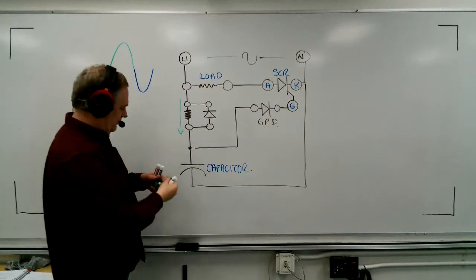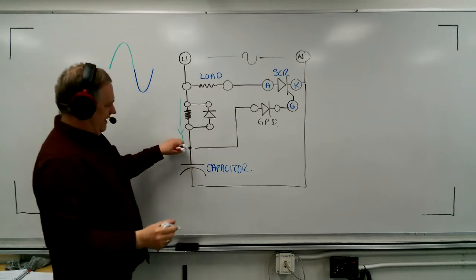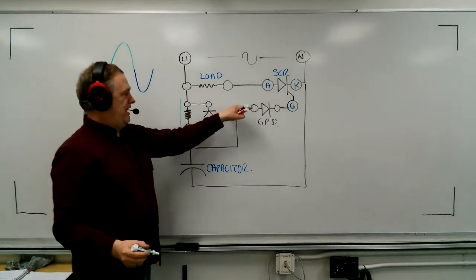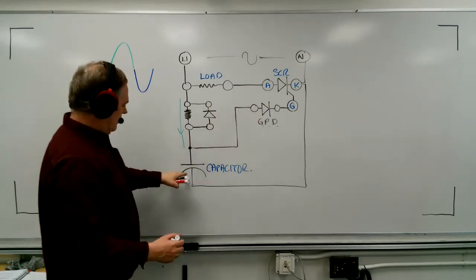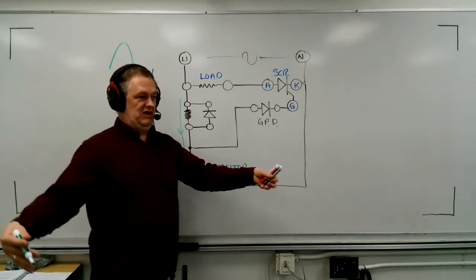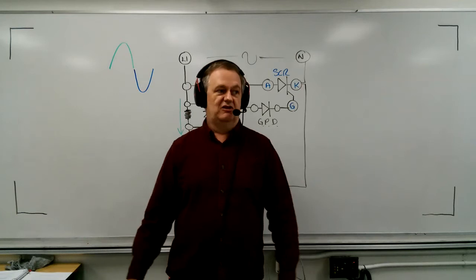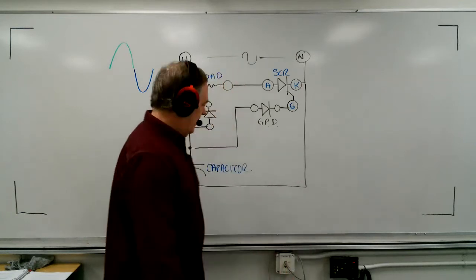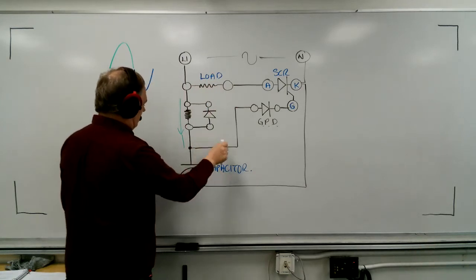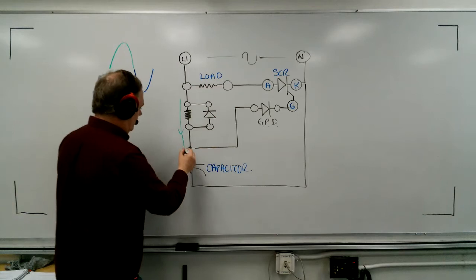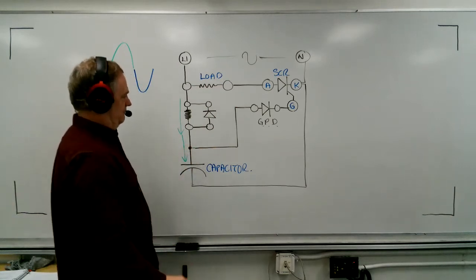But guess what happens when the current comes down to this point and it goes, okay, there I have a path where I have to overcome some voltage to get current to go that way. But here I've got this great big spacious, it's like a big barrel that's empty. This capacitor is just an empty barrel. And so before any current will go this way, because there's no opposition to it at all, I have to fill the capacitor. So it starts filling the capacitor, okay?